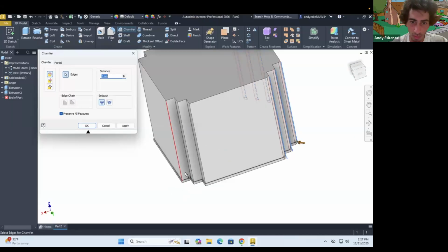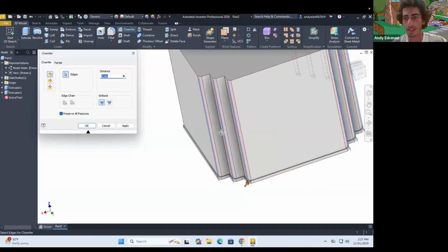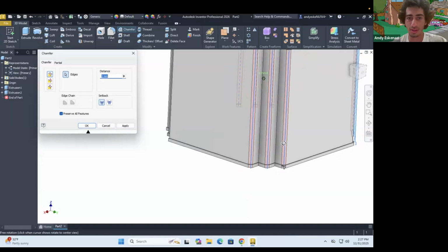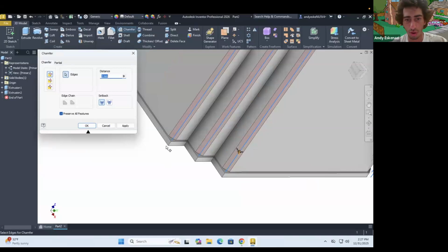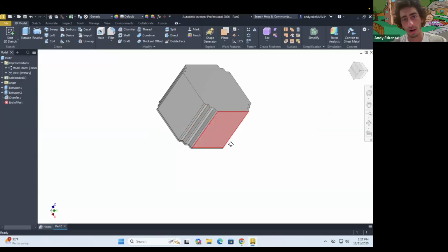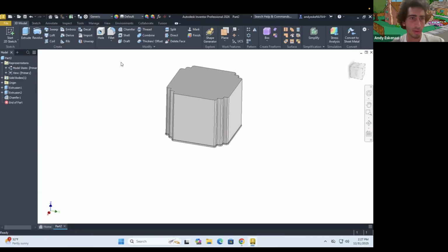By the way, one thing that you're already noticing is that these things are not tilted. But maybe I might need to edit this stuff. I'm trying out something right now, but we'll see whether I might change the order of operations in a moment. But okay, we got all of our chamfered edges. That's good. And now we're gonna use this command that's called draft. Where are you?